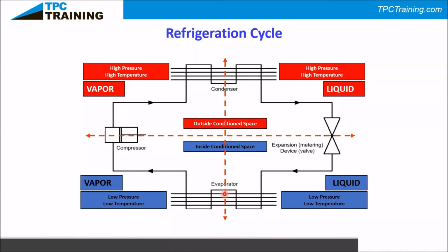Just that a lot of problems happen with that, and they're set up for two different functions. One, it can fail in heating mode, and one, it can fail in cooling mode. The manufacturers don't have them set up the same way. If you have a Trane air conditioning unit, it'll fail in cooling. So if it fails, you get cooling, you don't get heating. But for a Rheem or a Ruud system, you're going to get heating and you won't get air conditioning if the reversing valve fails.